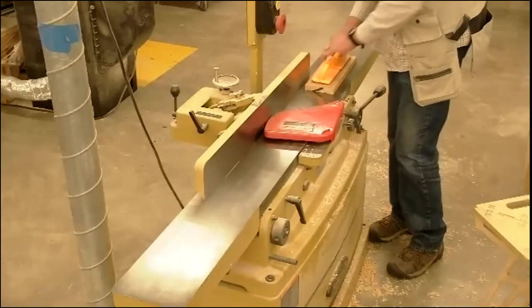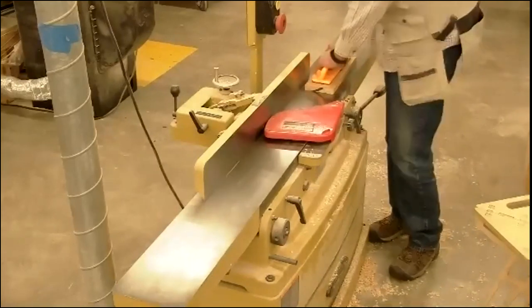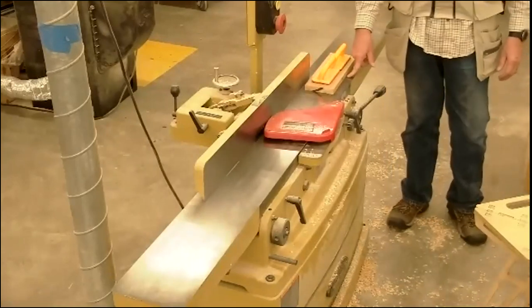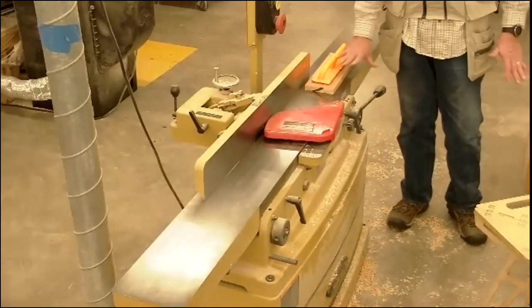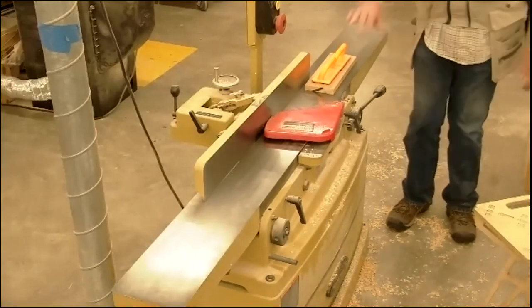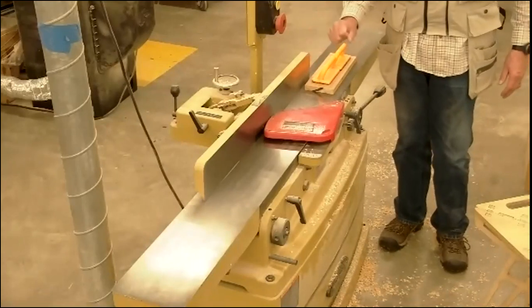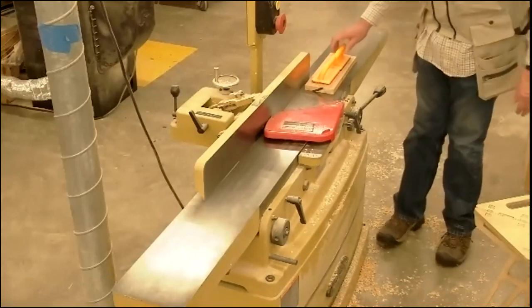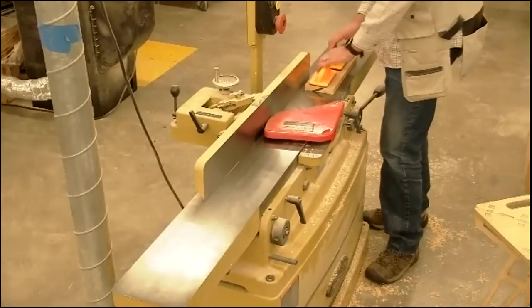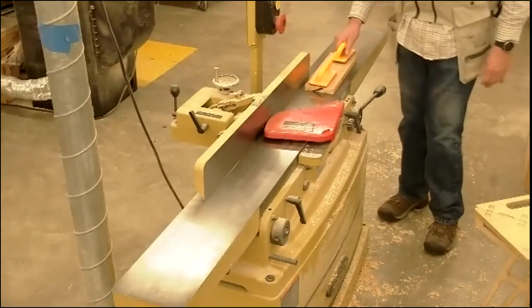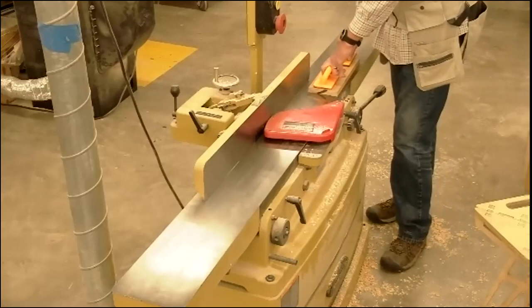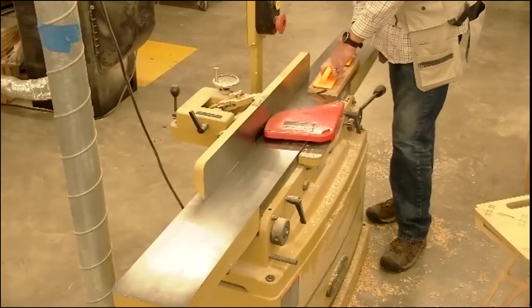If I put these pads kind of centered in the board, and I push down as hard as I can when I put it through the jointer, all I'm doing is pushing that bow out of it, okay? I don't want to force this board down and flatten it as it's going through the cutter head. It's not going to do any good because it'll just bounce back up once you take the pressure off on the other end of the jointer, okay? I also want to keep my pressure on the leading edge of the board. In other words, my rear pad, all it's really doing is helping me feed this into the cutter head. It's my front pad that's holding the board down, okay?